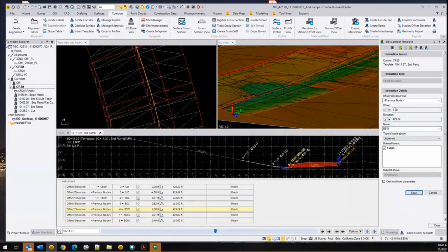All right, starting to look like we want. And the rest of these retaining curb need to check. Okay, yeah, they don't have a standard height, so we definitely need to enter at least the top of curb elevation here.